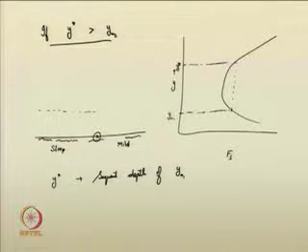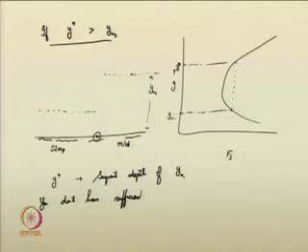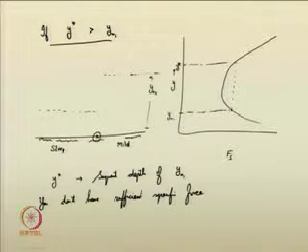If it happens in such a way that the normal depth yn2 is less than y star, or y star is greater than yn2, how does the flow get adjusted? Now, in this case, sufficient specific force is not available in the downstream section for the normal depth of the downstream section to cater the hydraulic jump. You do not have that sufficient specific force in the downstream section.